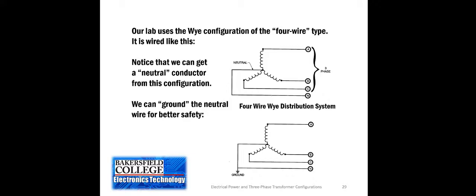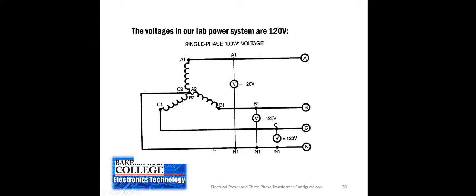But also, if it comes loose and tries to connect to one of the other phases, you're going to either have a phase to phase, which would trip a breaker switch, or you have a phase to ground, which is going to trip the breaker switch. So grounding the neutral is important for better safety. The motor or the transformer does not need that center connection to function, but there are advantages of making that the neutral connection or grounding it.